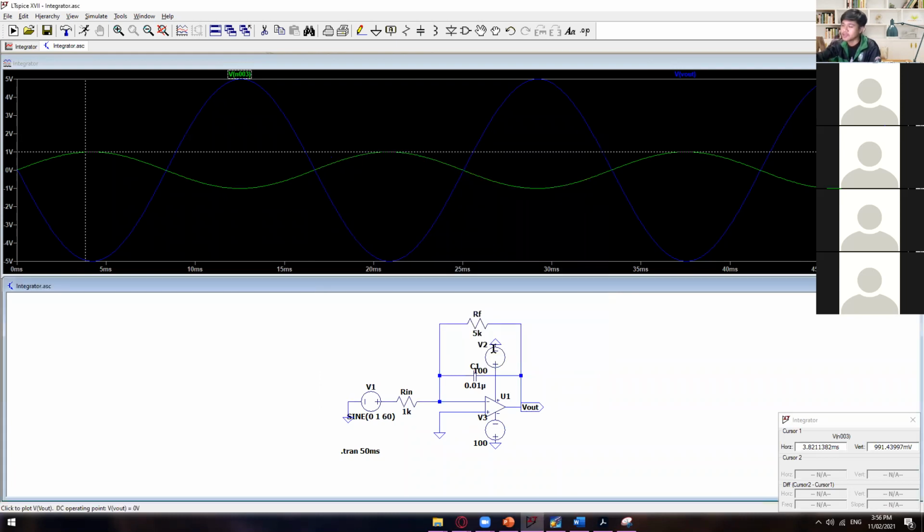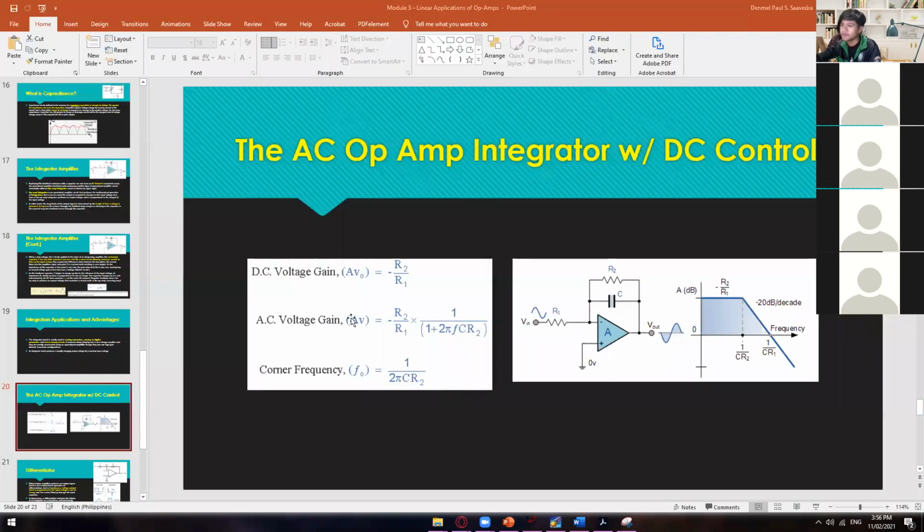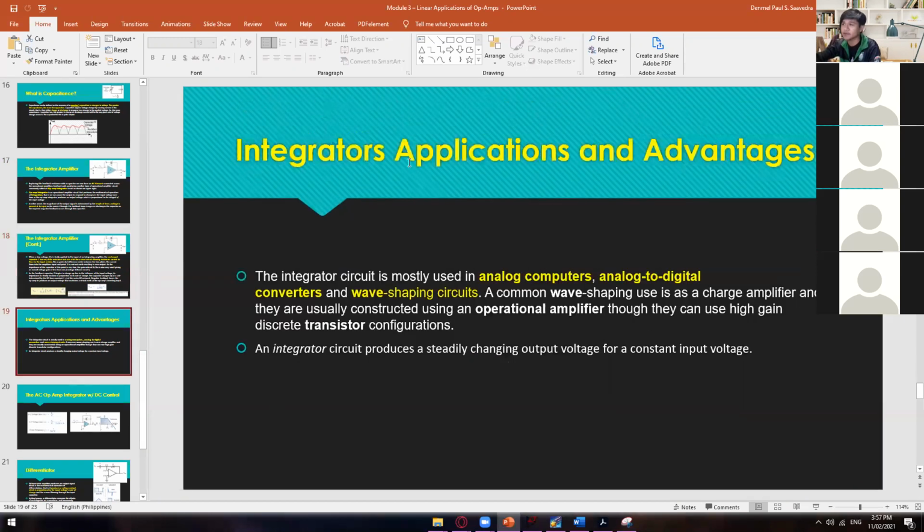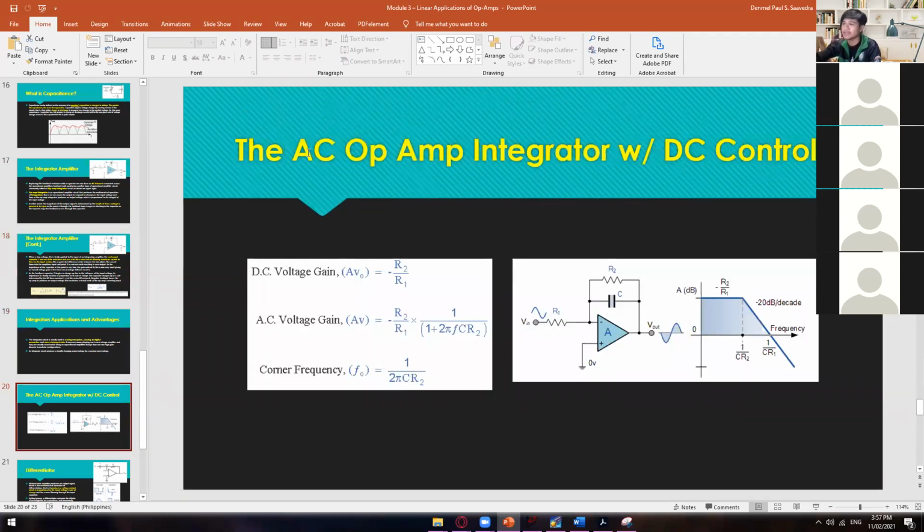All right. So an answer coming from Mr. Eda. So let me just repeat. This one is not a usable circuit since this one's like an open loop when it comes to having a gain. Okay, it's like 1,000 millions of gains. So instead, we have this kind of integrator, call it the AC Op Amp Integrator, for us to have more control of your outputs. Right?